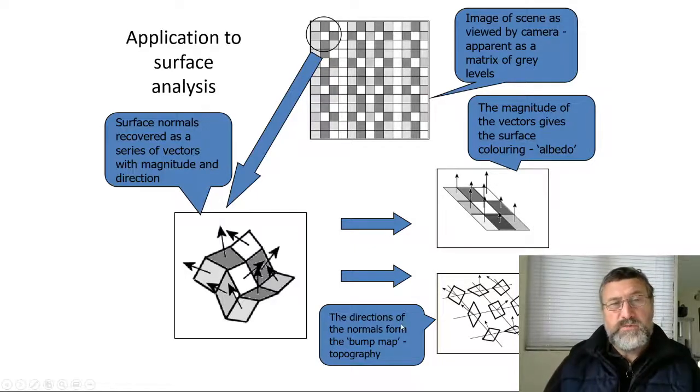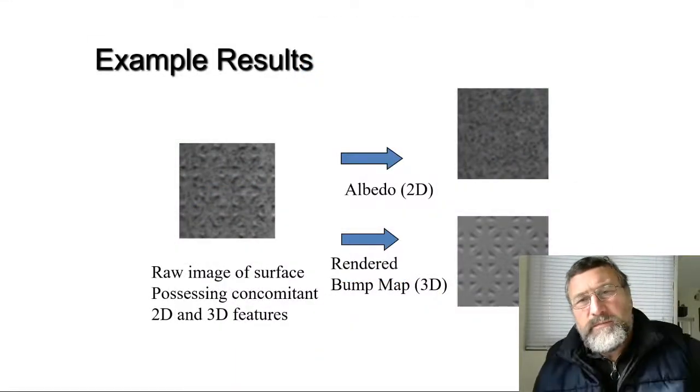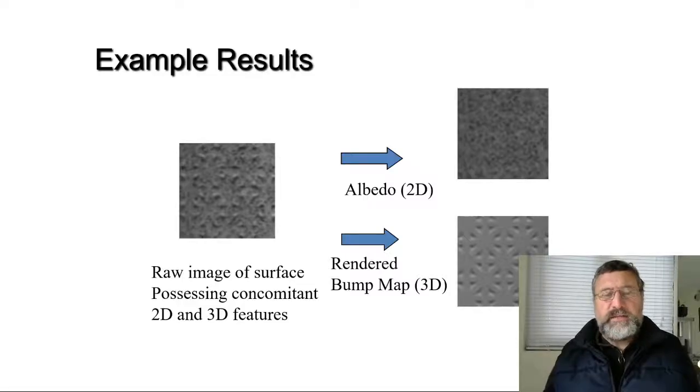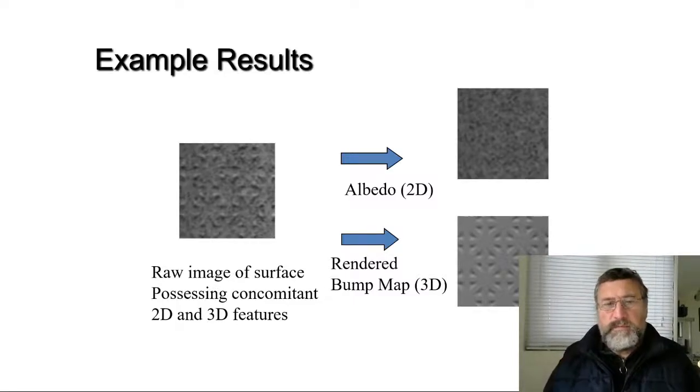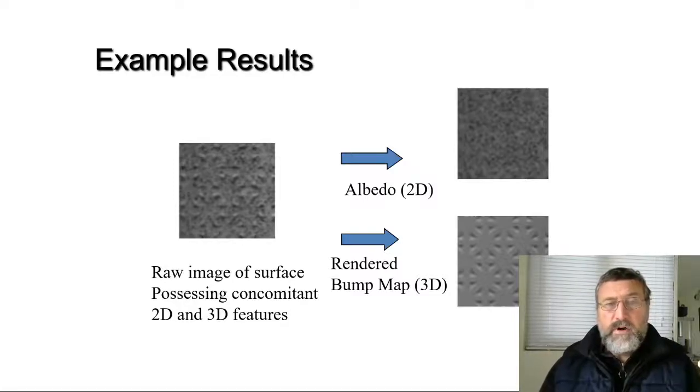It works remarkably well. It's quite a robust technique. We've got 6 lights in this setup to build in what we call redundancy, because this technique works with a minimum of 3 lights. But if we put 6 in, then even if we've got some sort of highlighting from the surface, which causes a problem for the system, we can just use a different combination of 3 lights. To avoid problems like that, which we call image artifacts, we use the combination of 6 lights. And also, we had a researcher who developed the first skin analyzer with me about 18 years ago, who discovered that for any convex surface, you can fully recover it with this technique using a minimum of 6 lights, which I thought was quite an interesting development.